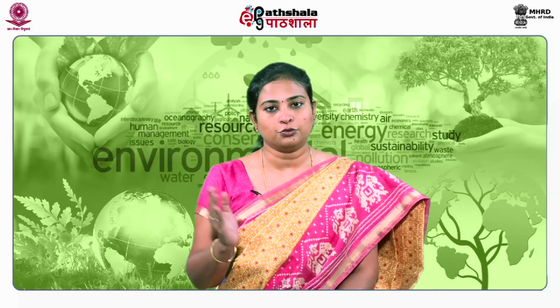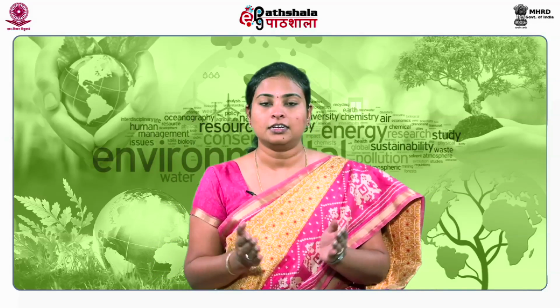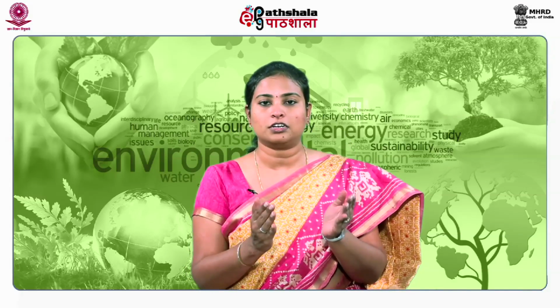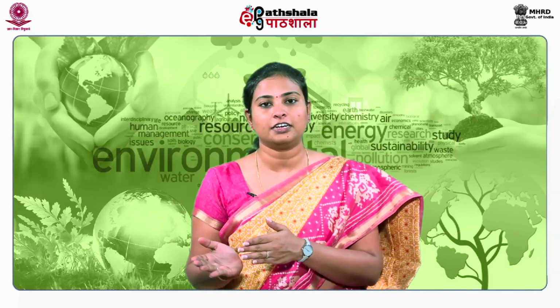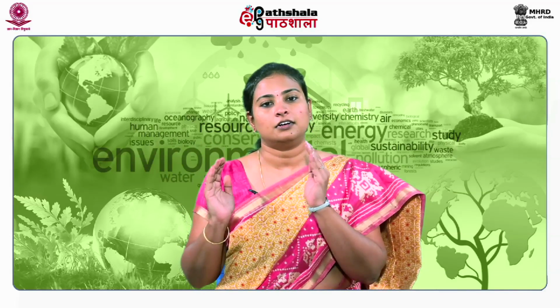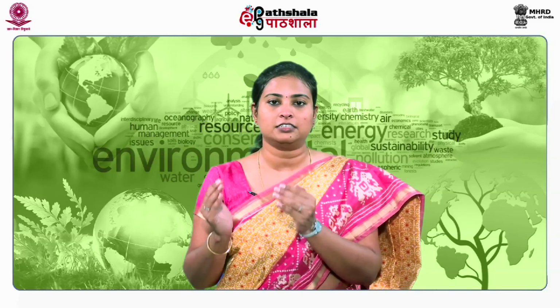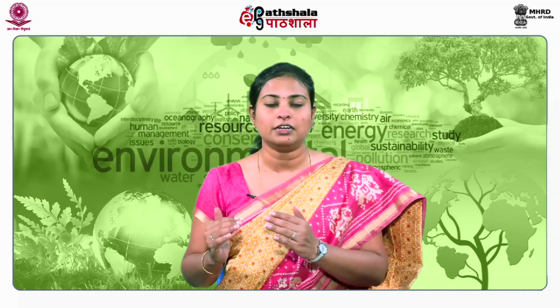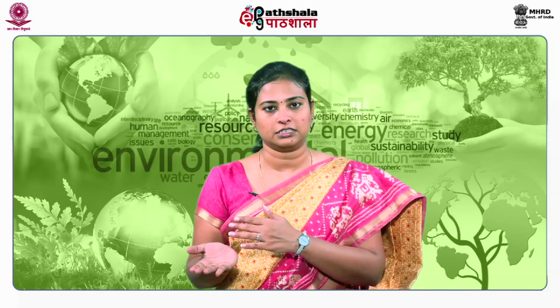The next unit within the activated sludge process is a secondary clarifier, where the treated wastewater along with the biomass is transferred. In the secondary clarifier, they are retained for a period of 2 hours, where the suspended solid materials settle down and the clear supernatant is taken into the next treatment unit.